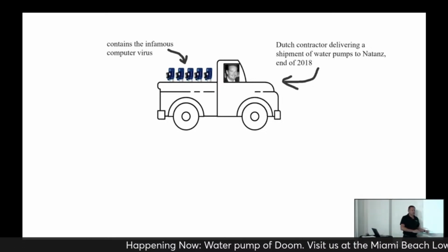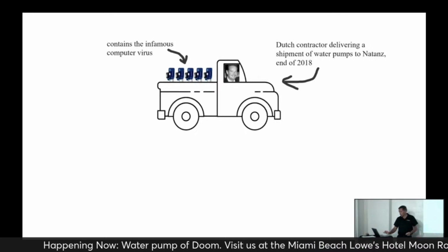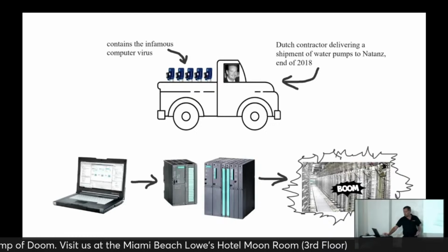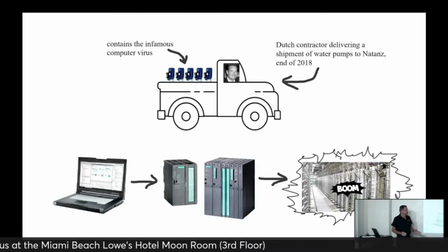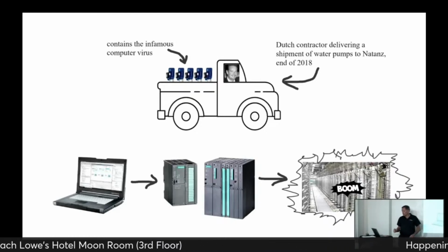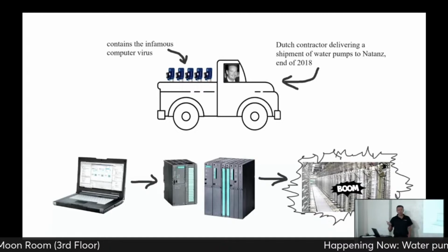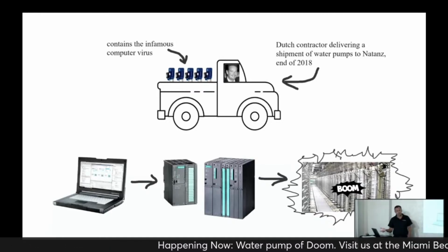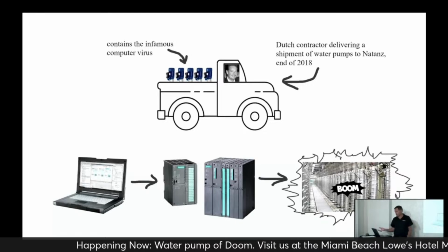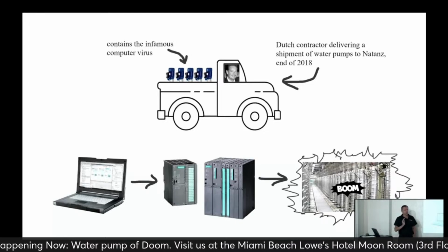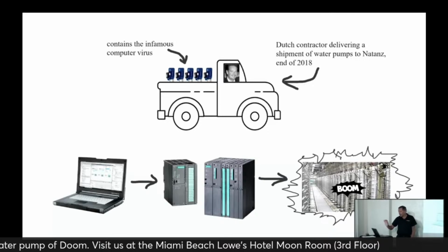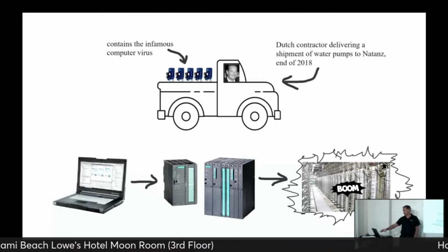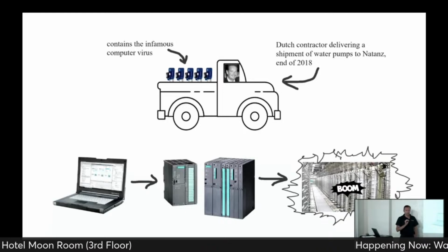Then what we know from the forensics about Stuxnet is how the compromise actually works. This is what you see down below. So we have centrifuges that are spinning out of whack. Then we have the Siemens PLCs that control these centrifuges, and we positively know that the malicious code got onto the PLCs via an engineering station.